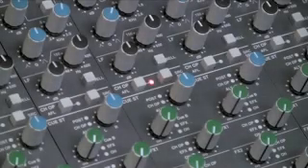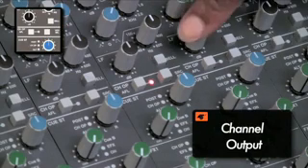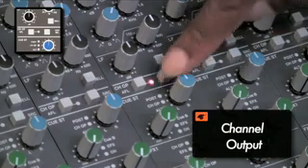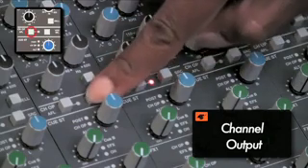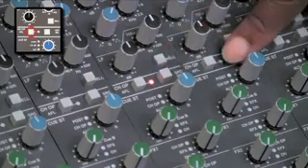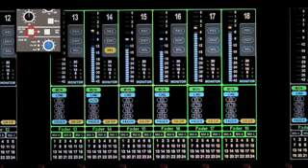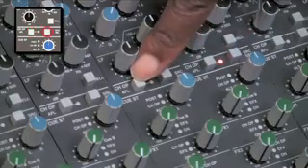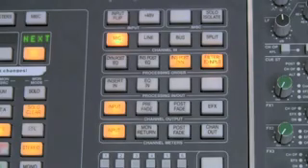Following the EQ section is our channel output selection. The channel output is normally used to feed the DAW input. The default signal is a post-channel fader feed, but the source select is used to select alternative channel output feeds. These include a pre-channel fader feed, a channel input feed, or you can activate an EFX send. All this can be graphically viewed on our TFT screen on the meter bridge. We use the AFL switch to monitor the channel output source as you toggle through the options. This is done with the source select button. On our center section, we have a single button selection for the 4 channel output sources: input, pre-fade, post-fade, and EFX.